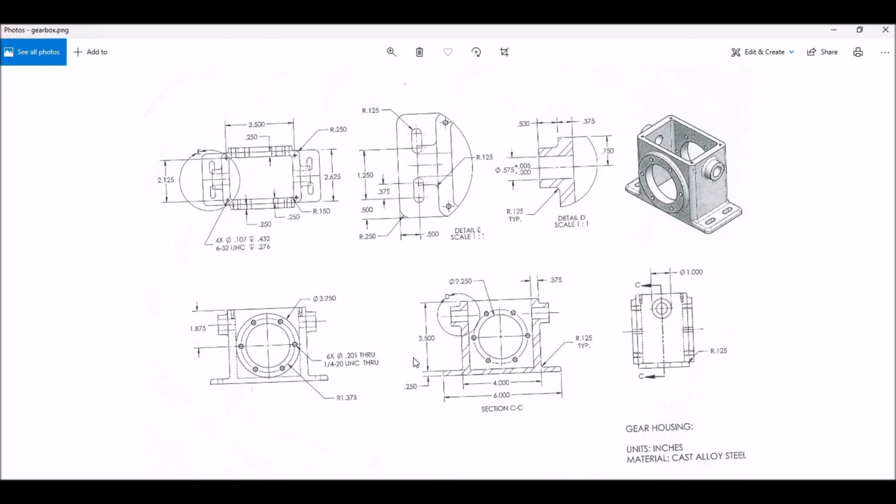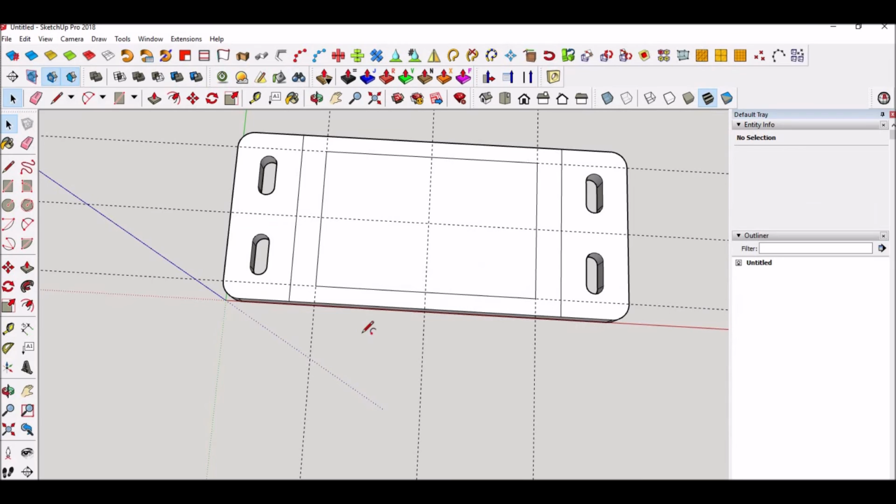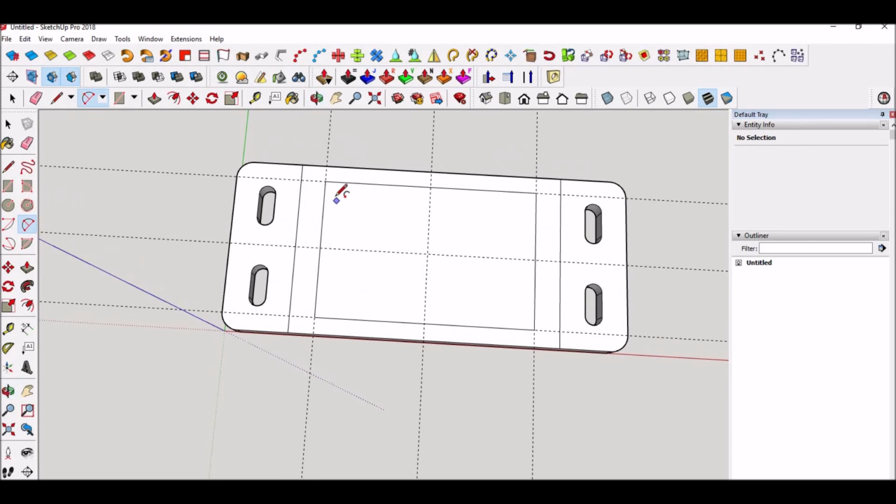Now, before we even extrude that, the radiuses are 1/4 inch here on the outside, but 0.15 inches on the inside. So, arc tool, make sure it's 48 sides. It is. Down in the bottom right hand corner you'll see that, but on my screen you will not, but on yours you will.